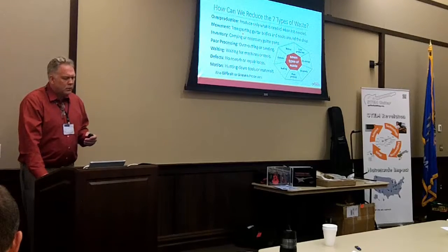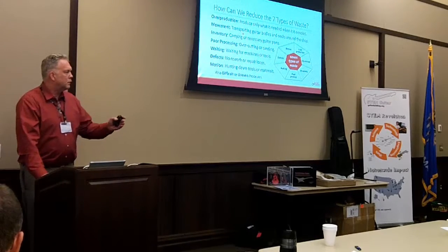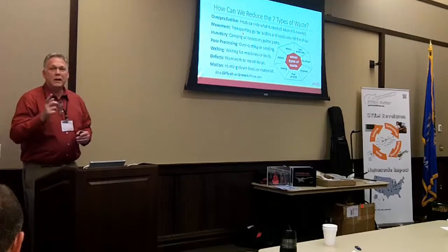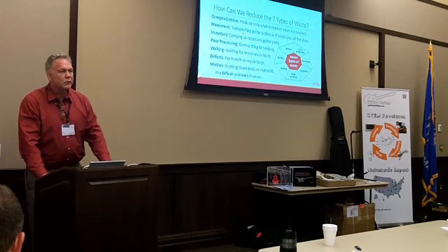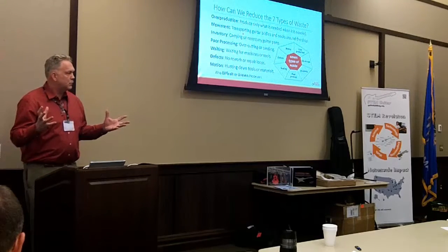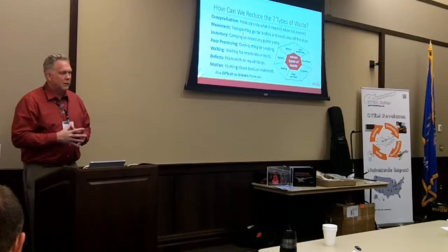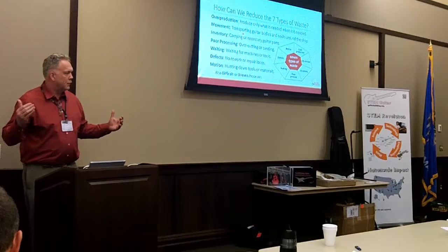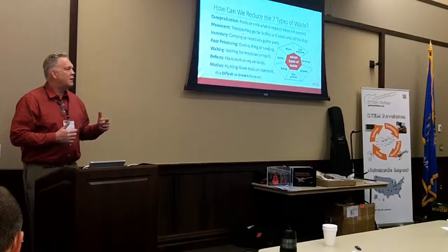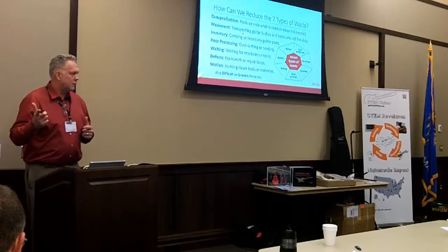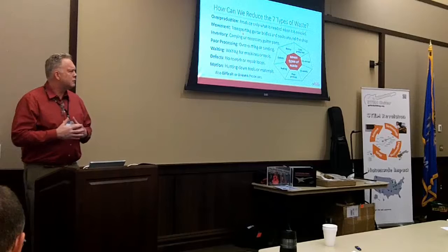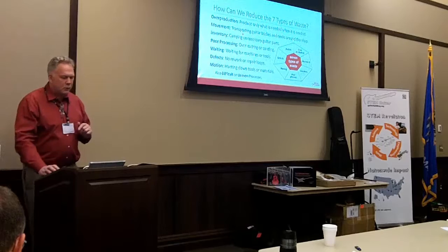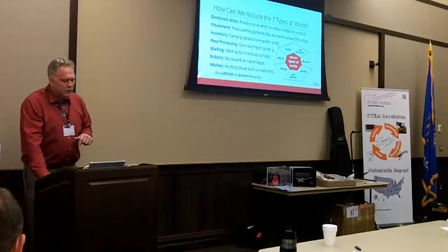This is where you transport guitar bodies and necks around the shop, going from shop to shop. How many have ever seen a spaghetti diagram? We had a spaghetti diagram that we did when I was at General Motors for one of our tail lamps, because we kept getting dinged. It was a Buick Crosscar. We kept getting dinged when we were trying to win quality awards because of the scratches on the component. And we found out that that thing went 8.3 miles through our factory before it got out the door. So there's all kinds of opportunity for failure when you don't have a process that has a very straight path out the door, or at least one loop or a horseshoe to make it happen.